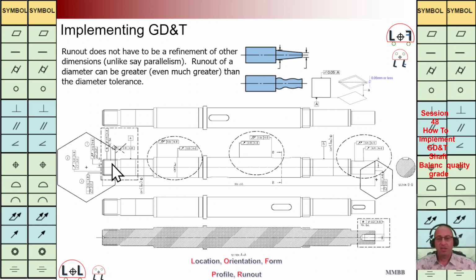And for threaded shaft and threaded hole, we are going to use this positioning control with this diameter symbol to control the coaxiality of that. We haven't talked about these key slots. We need to use feature control frames to control these two key slots.